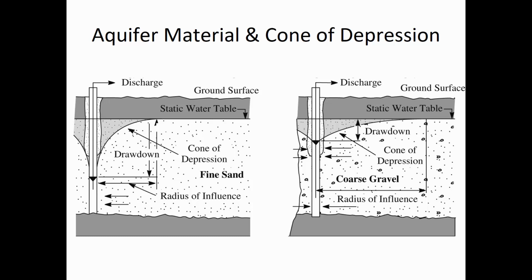What was the first part of what you said? Larger voids. Okay, larger voids, good. So if there's larger voids, then the hydraulic conductivity is higher, which means you need less delta H, you need less of a driving force to achieve a certain flow rate. Because remember, Darcy's law says Q is K A delta H over L.